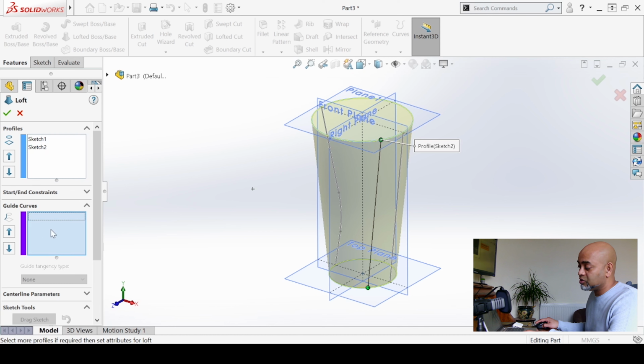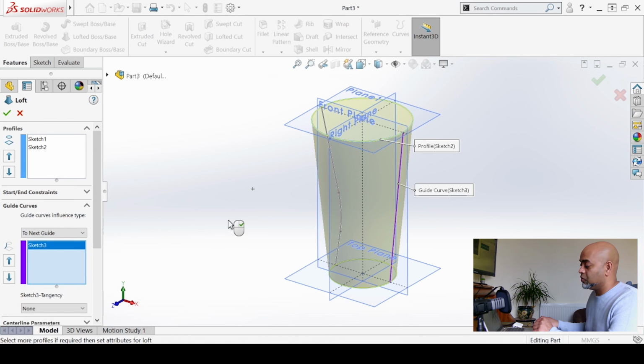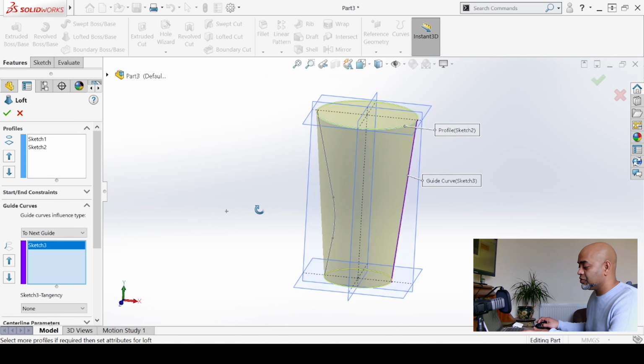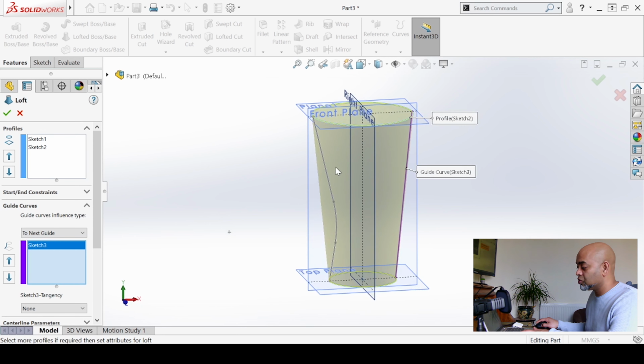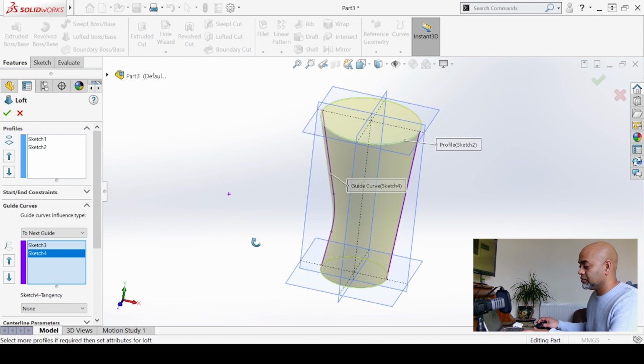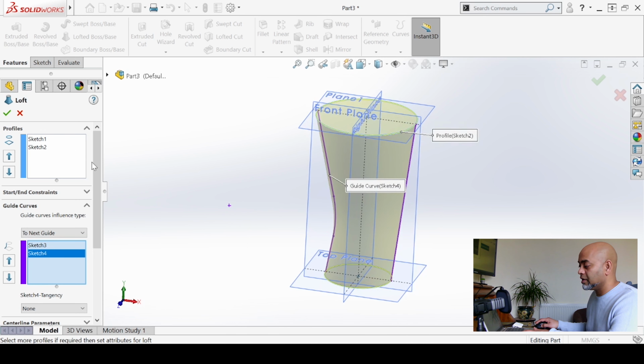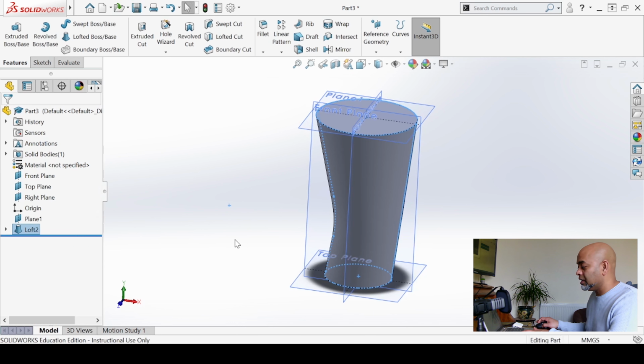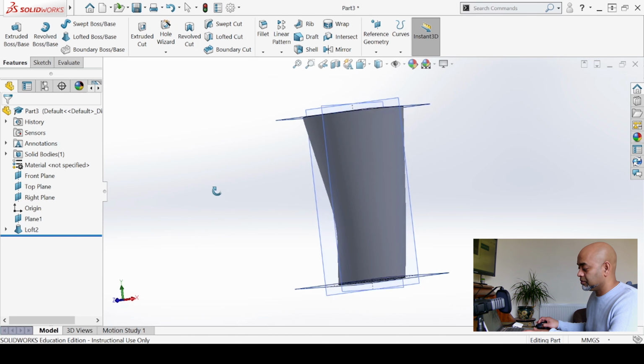So I'm going to activate that space, and I'm going to say, how about you draw me that profile through this line, and SolidWorks will comply, hopefully. Not that line, that was the preview. This line here. And it's taking that in and saying, right, okay, we have done that. And that's not all of it. I want it to go through that line as the waistline, and so as this profile which we created. Look at that. So it's going through both of those now. I can green tick to confirm, and that gives me the profile I was after.